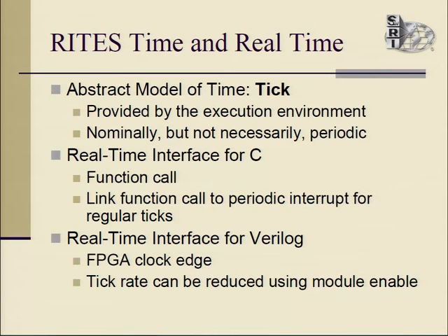So if you implement the timing program in C, it's going to be realized as a function, and the tick will be the interval of a function call. So for every time tick, every interval, you call the function, and it will handle everything of keeping track of time and executing the sequence you've asked for. This can be made very periodic, even on a busy processor, by, say, tying that to a periodic interrupt.